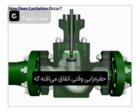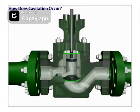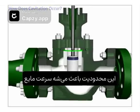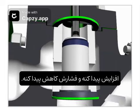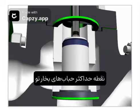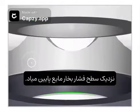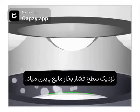Cavitation occurs as a liquid passes through a restriction, such as a valve. The restriction causes the liquid's velocity to increase and its pressure to decrease. The point of maximum velocity and minimum pressure is called the vena contracta. Vapor bubbles form in the liquid when the pressure falls to near the level of the liquid's vapor pressure.